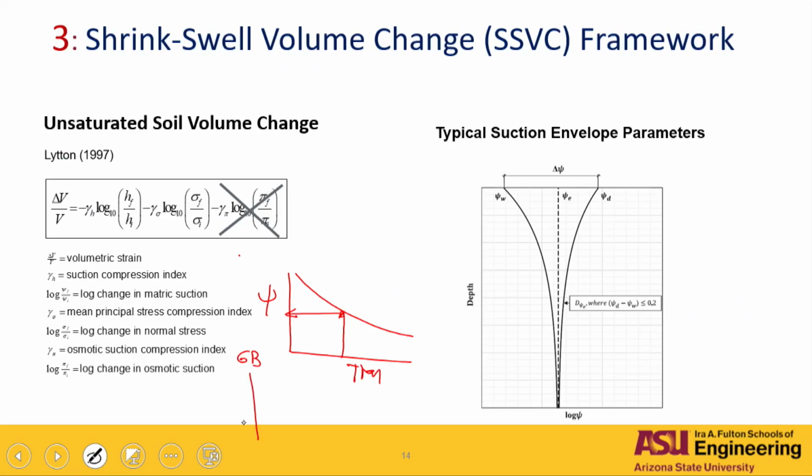And when you compacted that, you compacted it at optimal moisture content, right? Let's say that corresponded to, if you get to the degree of saturation versus suction soil water characteristic curve, the granular base material compacted at about optimal moisture content is, I always say, between 75 and 85% degree of saturation for all the soils pretty much, right?